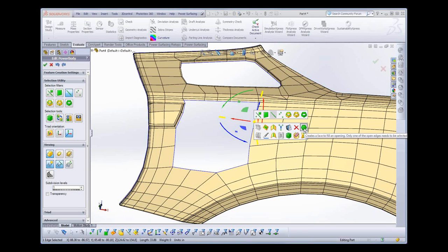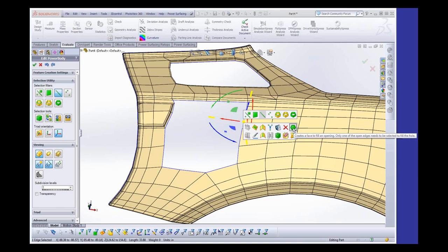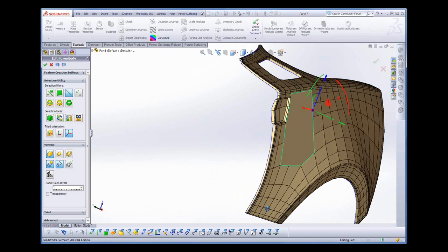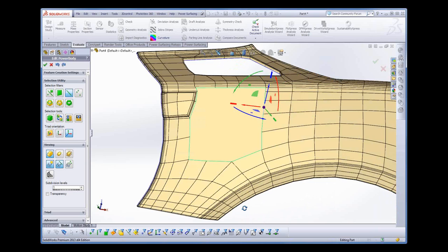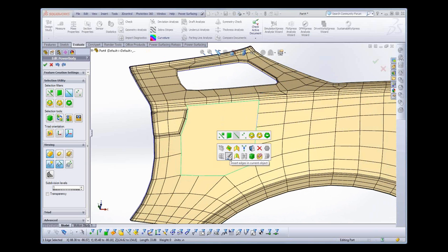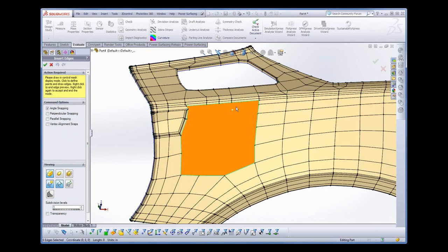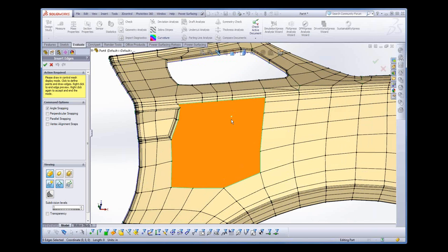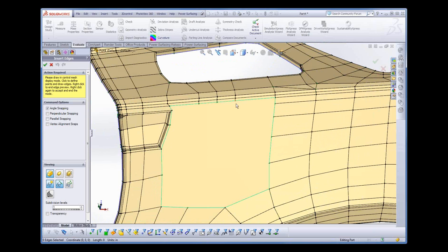So this is our fill face tool. But the problem is that it sort of stretches across just willy-nilly, wherever the points happen to be, that's where it's going. So just like on the spoon, we're going to want to recreate some edges. And I may have to move in here to get my snaps in good position. I need to undo that. I've gone too far on it. I wasn't watching my snaps.